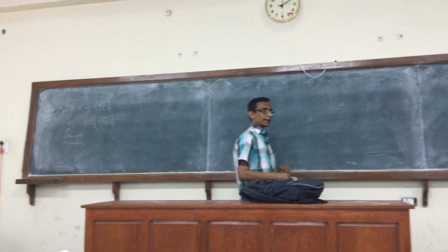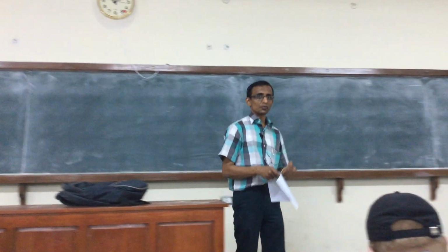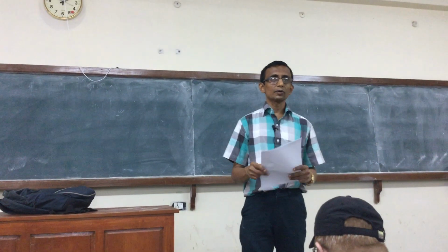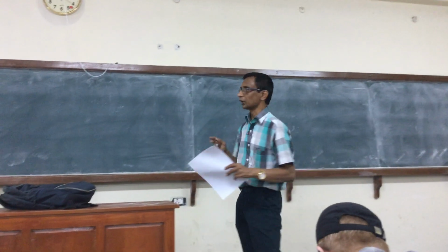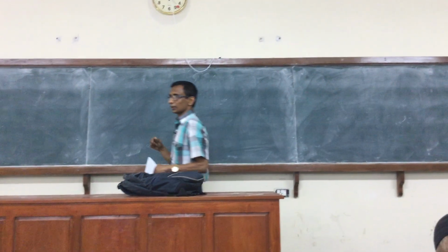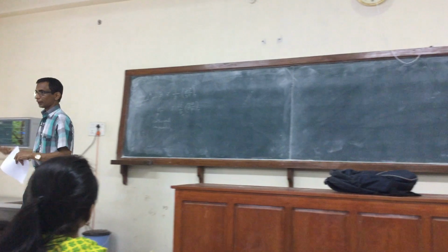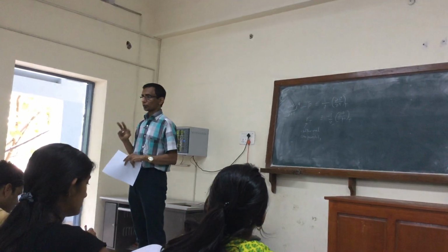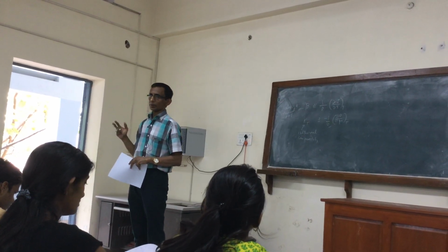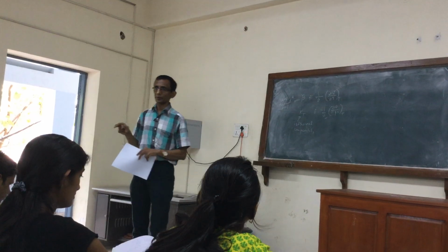And you can see that there is a negative sign in the definition of isothermal compressibility, so as to make the coefficient positive, because we know that dP by dV is less than zero. So dV by dP is just the inverse of that, it's also less than zero. So this would ensure that the isothermal compressibility is always positive for a substance.